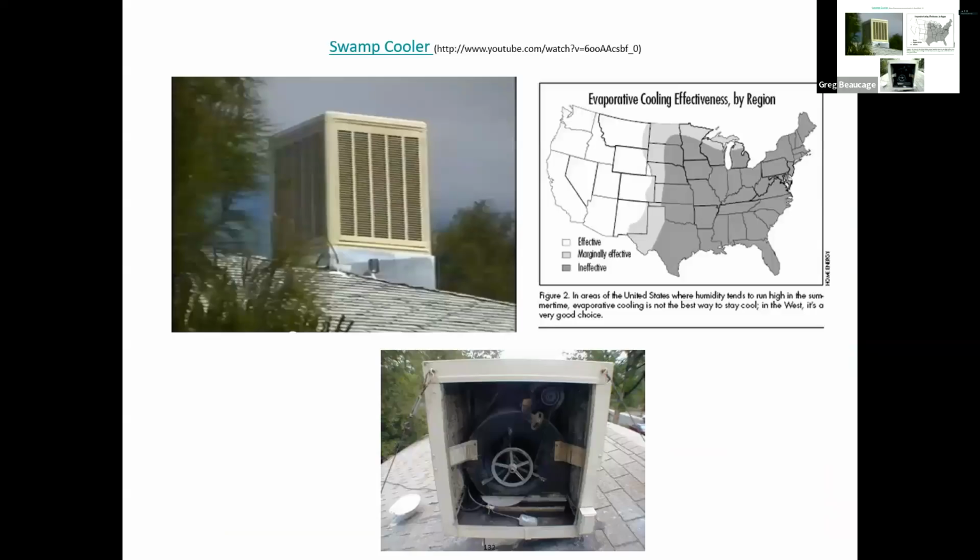If you go to New Mexico, like Albuquerque, I lived in Albuquerque for a while, and then California, it's dry, right? So you need a certain relative humidity in order to use this thing. Basically this is called a swamp cooler, and it's just a drum with a water bath at the bottom. The air flows through it and evaporates the water.